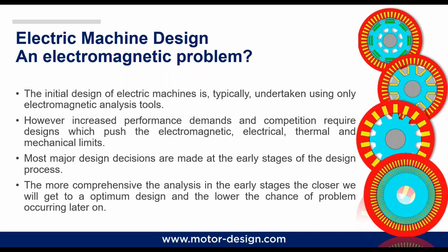However, as we increase performance demands and there is more competition in terms of different motor designs, we have to try to push the design limits in terms of electromagnetic, electrical, thermal, and mechanical performance. A lot of the decisions are made when we start the design, so at the early stage of the design process. So really what we need to do is to try to understand how our electric machine design performs, not just in terms of electromagnetic behavior, but in terms of the multiphysics behavior, right from the early stages of the design concept. Why do we need to do that?